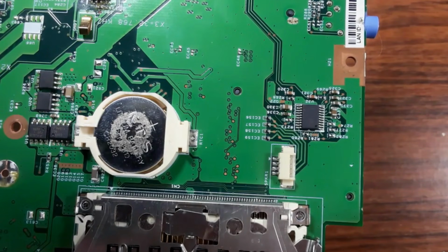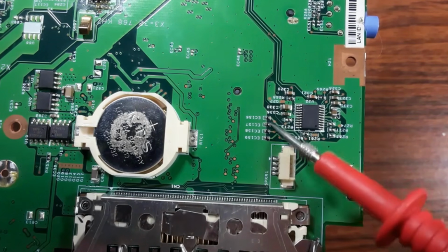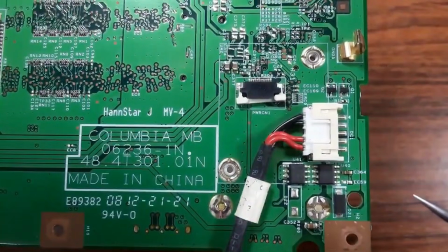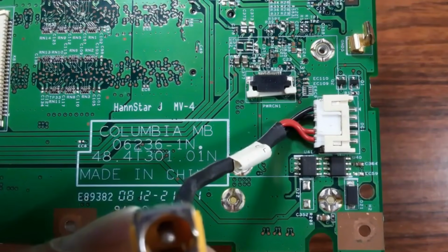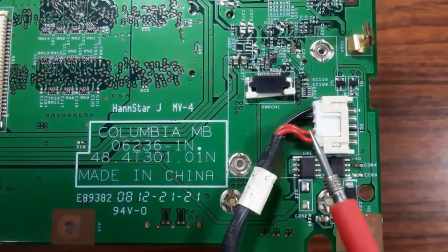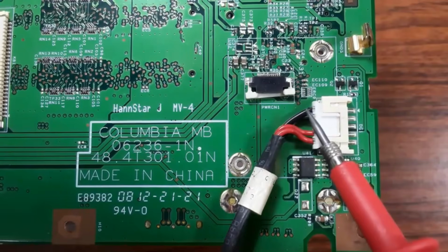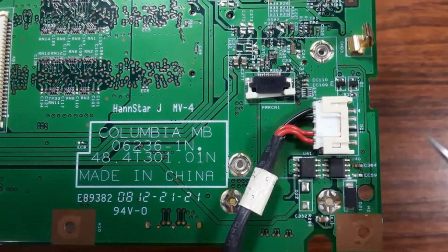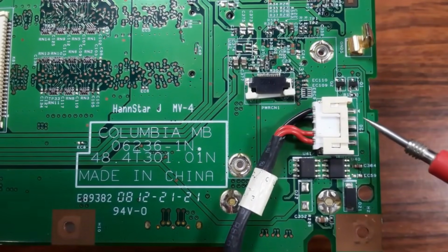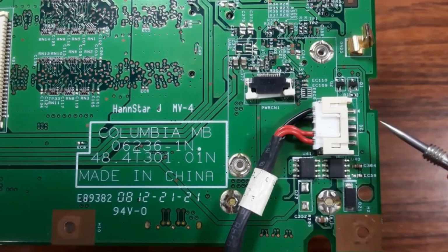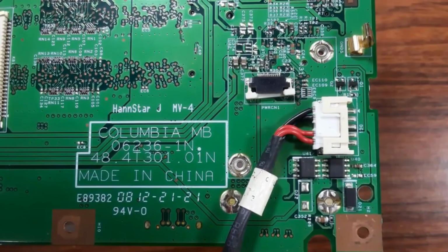But without knowing about buses and how to track signals, you cannot imagine that these resistors are connected to this. Okay? So for here, as you can see, we have the power check. Here we have 19 volt. Here we have the red wires and here the black wires. Means in these two terminals, we will get 19 volt. And of course, the black terminals are connected to the ground.